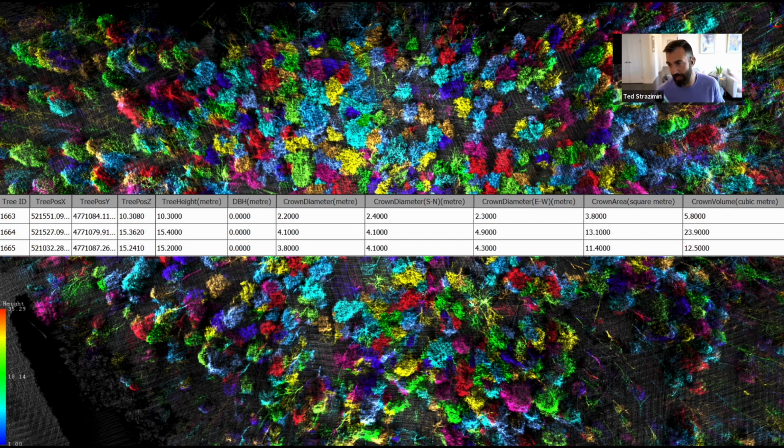But LiDAR is, I think, a perfect tool in that situation, because you can use it on the mine itself, on the pit, and get the topography and all those other use cases that I showed earlier. But then you still have it for this type of application as well. And you can always combine photogrammetry and LiDAR if you want a colored point cloud. It's just a matter of collecting an RGB version of the data set, a photo version, and then the LiDAR version, and bringing them back together. And software like LiDAR 360 can help you do that.